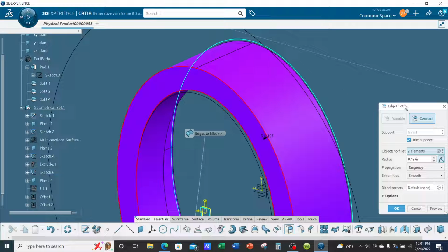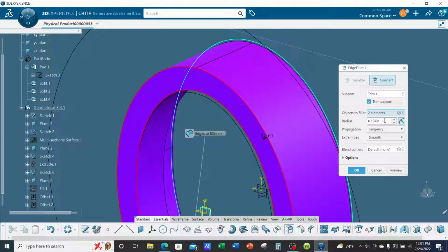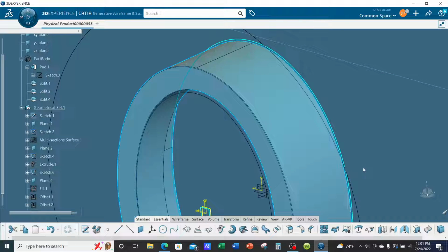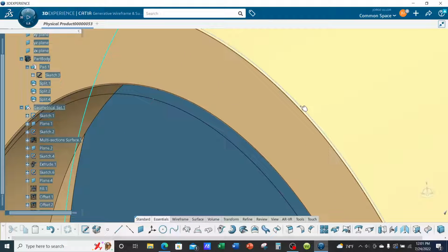Okay, and I'm going to go with a fillet of, I don't know, 1/8 of an inch, 0.125, so 1 divided by 8, 1/8 of an inch, and then click away, and it'll convert it to a decimal, 0.125, and OK. And now we have our fillets.